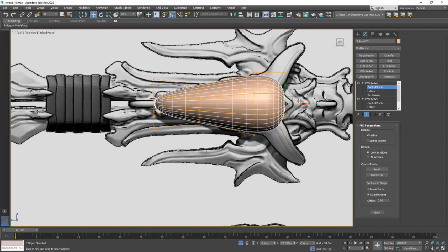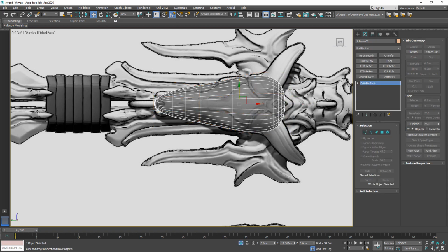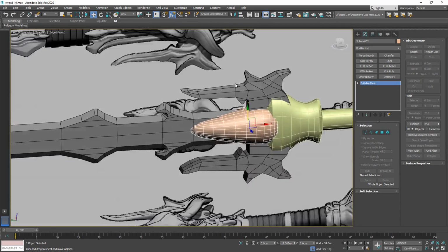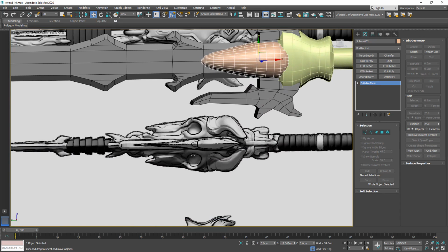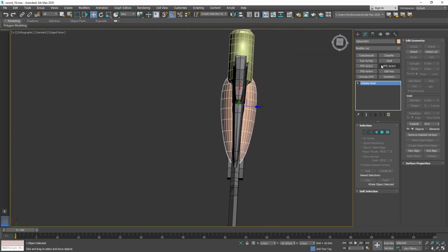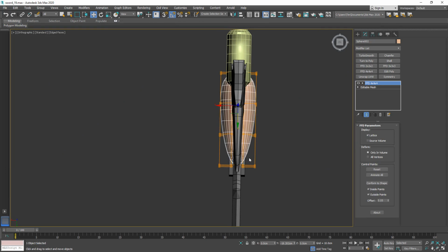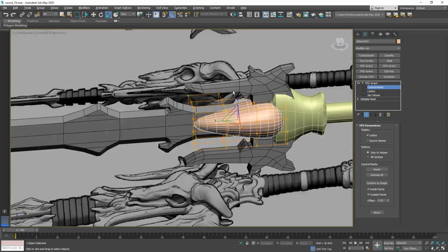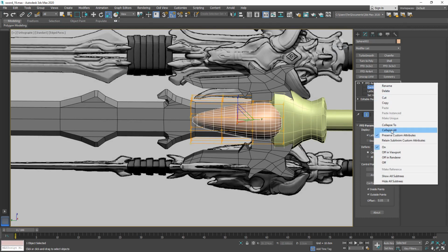And essentially, we don't have to be perfectly accurate here because we're gonna do the majority of the sculpting in ZBrush, where we also have move tools and all that. But let's just get some basic shape here. For example, this here, let's add another FFD modifier. And let's go over here to those control points. Actually, I'm gonna select the ones here on the side, left and right side only, and then on the x-axis. And that's already enough for this piece here.